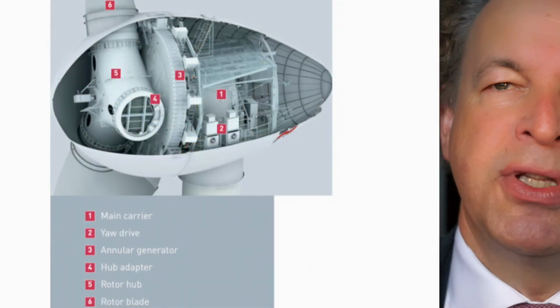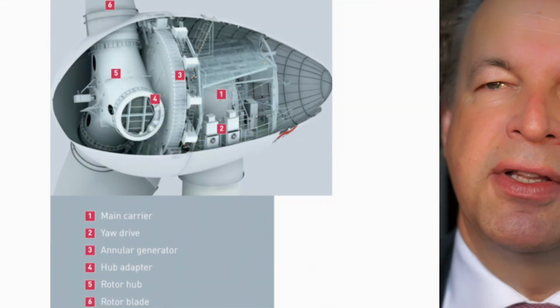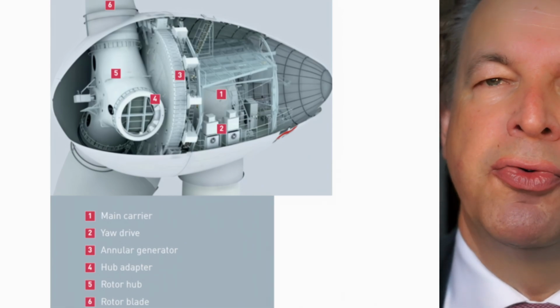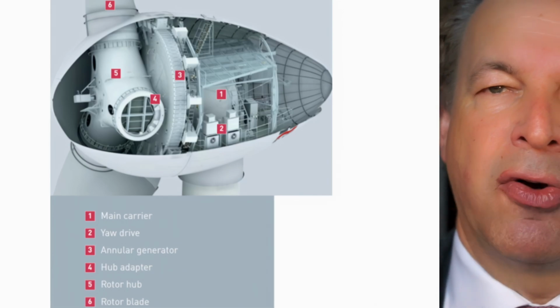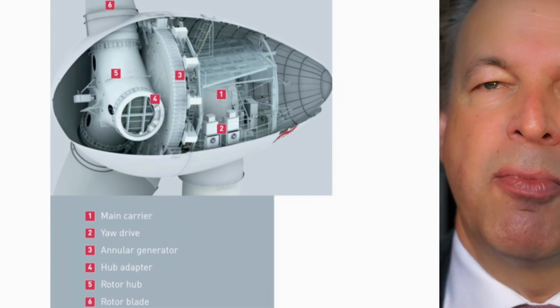This is now a wind turbine with a generator with a high number of poles, so you don't need any gear anymore. So you have less problems with the gear, less maintenance, and also a higher efficiency. The problem is it is more heavy and more costly.